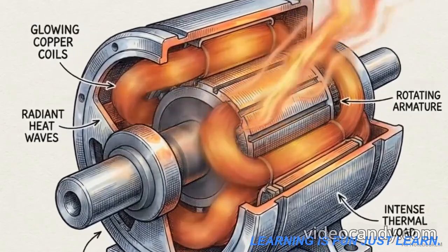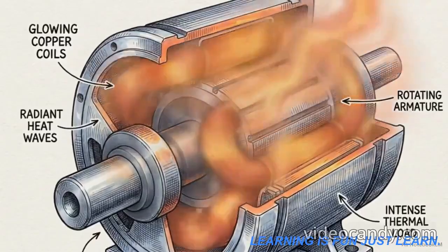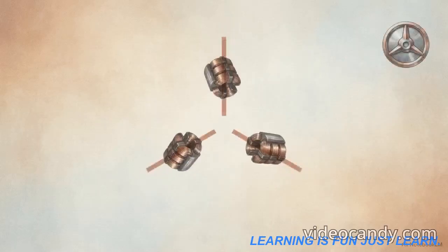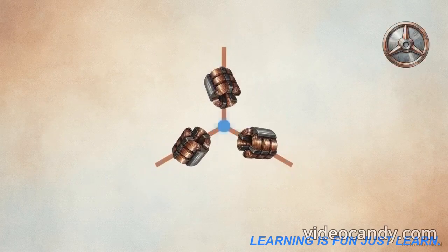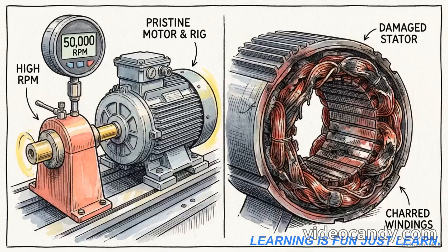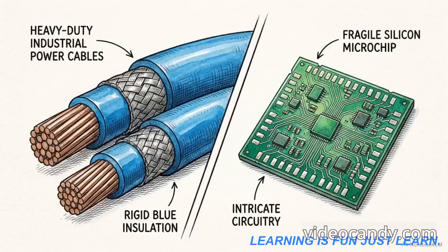Because the circuit forms a continuous internal track, high-frequency parasitic electrical currents can circulate entirely within the motor, leading to excess heat and wasted energy. The Y winding operates differently. Its branches meet at a central point, but remain open-ended at the power connections. This layout physically prevents those parasitic currents from finding a closed loop to circulate in. Selecting the right motor topology forces an engineering trade-off, balancing absolute top-end speed against the daily cost of internal parasitic losses.